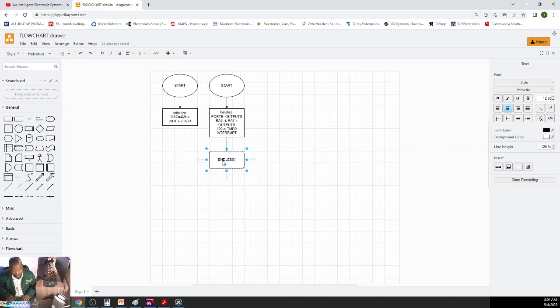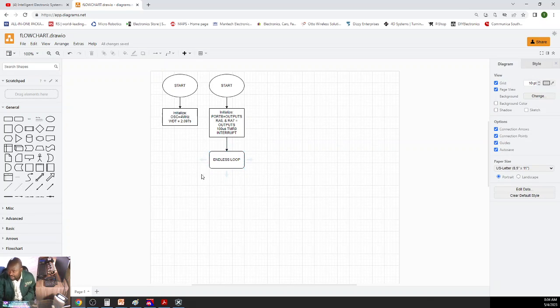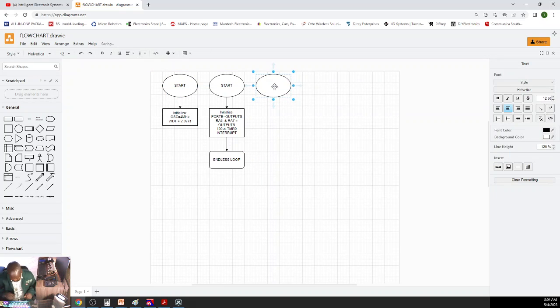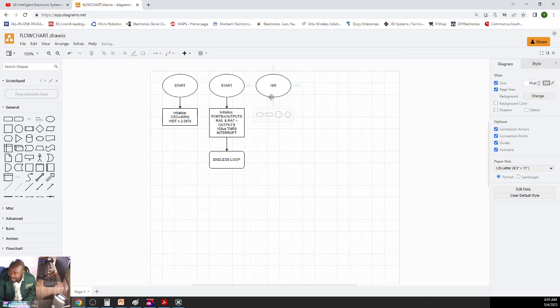Endless loop. Now I go into an endless loop, meaning just main, go to main there. I've set up my timer 0 interrupt. When I get an interrupt, interrupt service routine, origin 04. When I get an interrupt, I have timer 0 interrupt. When I get an interrupt, I need now to check which 7 segment is on. I just need to toggle between the 2 7 segments.